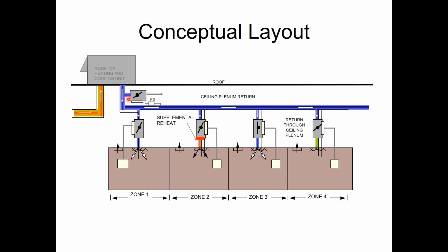The damper you see up here, we did not have that on the VAV system last week. That's different. We have that on here because as these zones start to throttle their dampers back, the static pressure is going to be building up in this duct system. And when that static pressure builds up, I've got to do something about it.